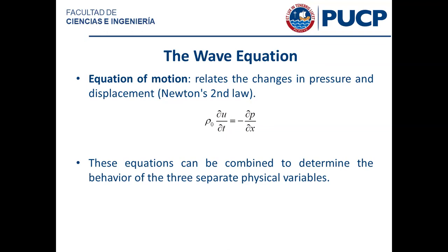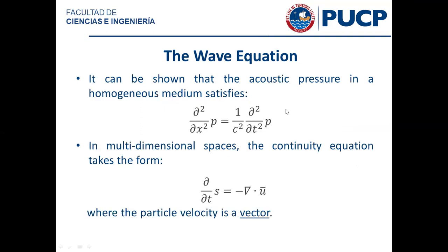So we have three equations and we have three unknowns, and we can actually try to come up with a solution. And yes, exactly, Emilio, mass times acceleration equals force, which is what you typed in the chat, right? So we can try to combine these equations, and if we do, we can show that the acoustic pressure in a homogeneous medium is going to satisfy the equation that we have in here.